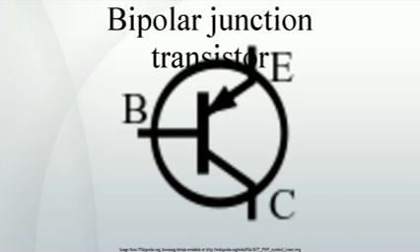Power BJTs are subject to a failure mode called secondary breakdown, in which excessive current and normal imperfections in the silicon die cause portions of the silicon inside the device to become disproportionately hotter than the others. The doped silicon has a negative temperature coefficient, meaning that it conducts more current at higher temperatures. Thus, the hottest part of the die conducts the most current, causing its conductivity to increase, which then causes it to become progressively hotter again, until the device fails internally. The thermal runaway process associated with secondary breakdown, once triggered, occurs almost instantly and may catastrophically damage the transistor package.